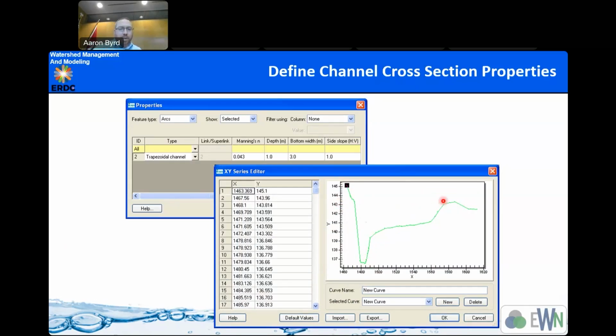So you need to have your starting and ending points be the same. Does that make sense? It doesn't have to be exactly the same, but if water ever got up to here, you'd be in trouble with your cross section. If water never gets up there, you'll be fine. Right? So what I'm going to assume is that you have a vertical face over here. Right here is where you define whether it's trapezoidal or a breakpoint cross section.